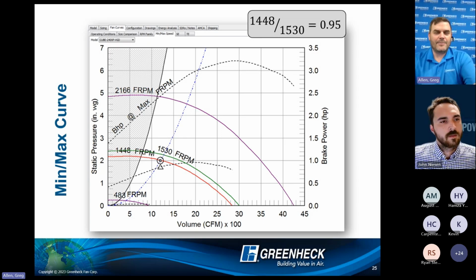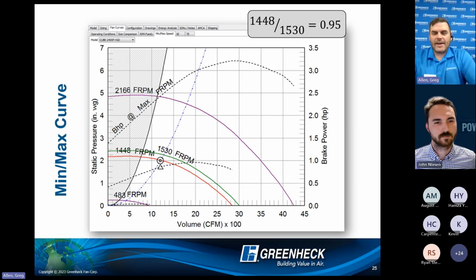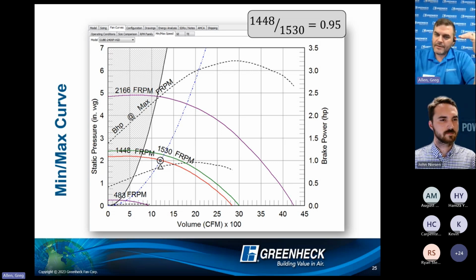Now, when we start tying this back into application, boy, there are so many different applications where this is beneficial. I could have a normal air movement for a stairwell, but then I have an alarm point where I'm maintaining 0.1 inch in a stairwell when there's a fire condition, right? Now I can just turn a fan on to a normal set low point, or if the fire alarm goes off, I have a constant pressure control, a differential pressure transducer, and I can modulate the airflow to maintain that 0.1. So that's just an example of where an EC motor or VFD is very nice, right?